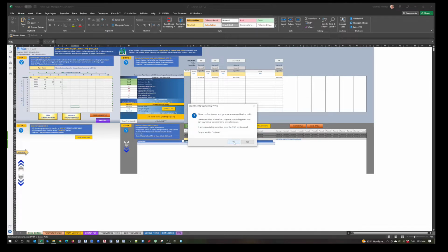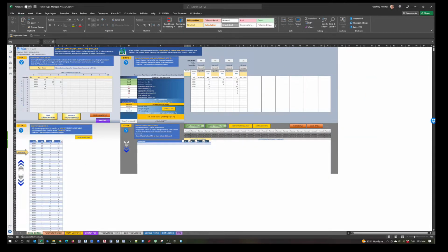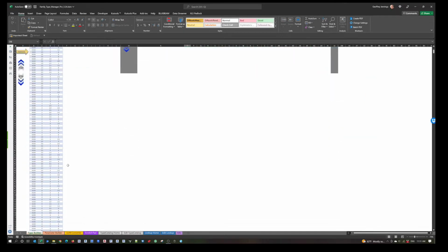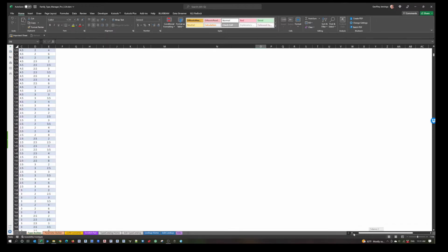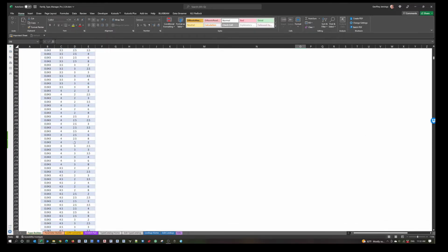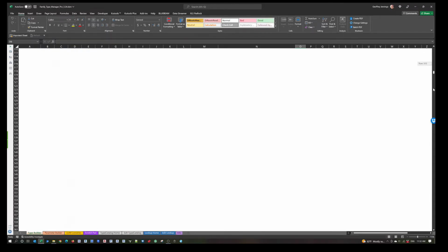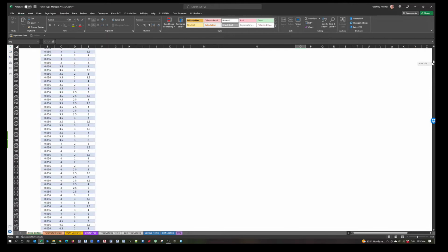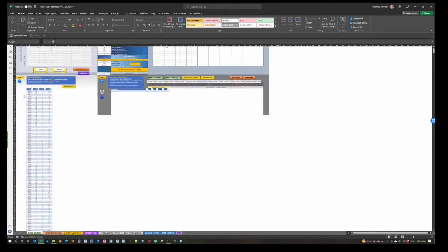And it's going to let us know a warning message about proceeding forward. Click OK. And it's done. It's just generated 420 unique combinations that are available by this manufacturer. So if I scroll down here, and I'll zoom in, you'll see here we have every single mill thickness, width, leg 1, leg 2 measurement for the entire project, all the way through here.